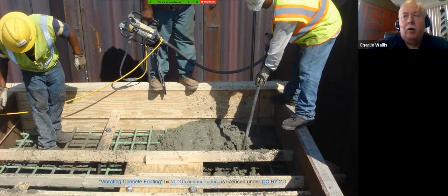And this is an important part of placing concrete, is vibration of the concrete. It's a two-man operation. You can see here one individual is holding the power, and then that's applied to this vibrating rod, which is inserted into the concrete, and that helps to disperse it uniformly. It gets it into all the gaps, the nooks and crannies, and it helps to prevent honeycombing.